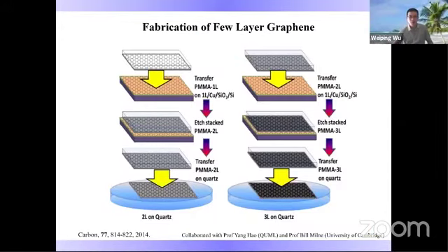By growing CVD graphene on the wafer, we are able to build so-called artificial graphene using a newly developed process at the University of Cambridge, by repeatedly transferring single layer graphene grown on copper onto a silicon dioxide silicon wafer. Repeating the process gives us a very special opportunity for stacking graphene towards bilayer, tri-layer, 4-layer, and 5-layer graphene.